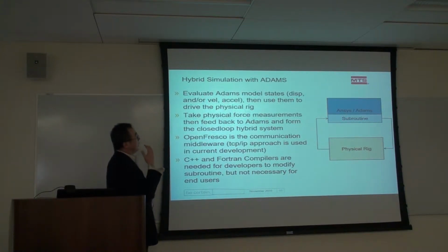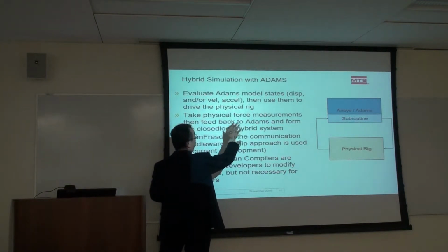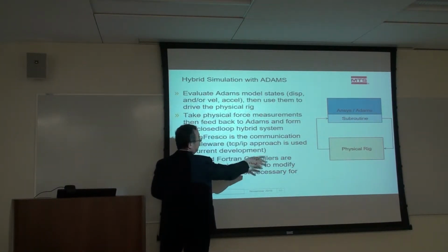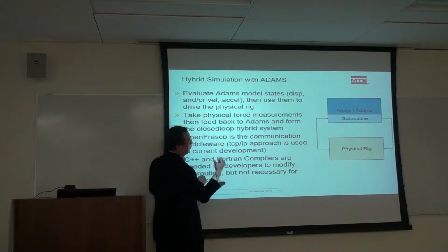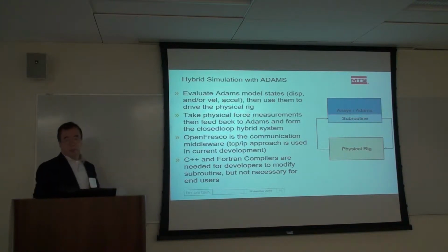Adams can model the vehicle, then the commands are sent to OpenFresco, then sent to our test rig, so we use OpenFresco to do hybrid simulation for ground vehicles.